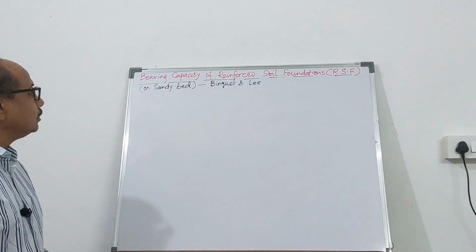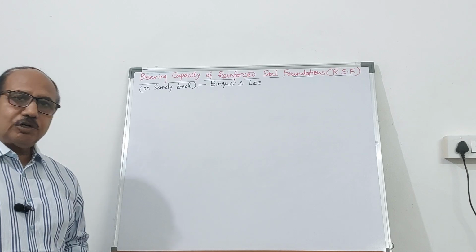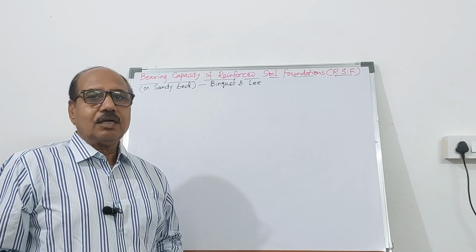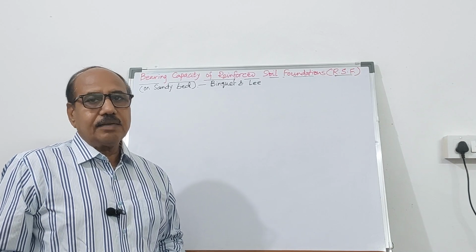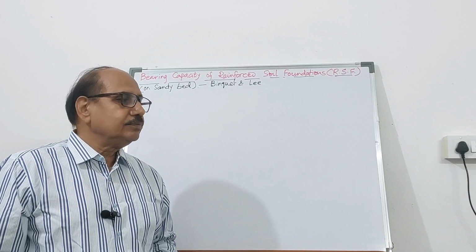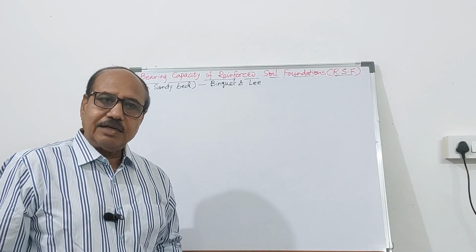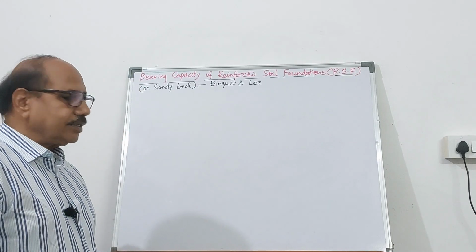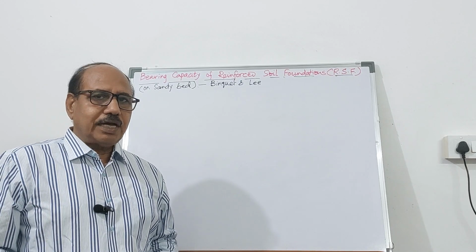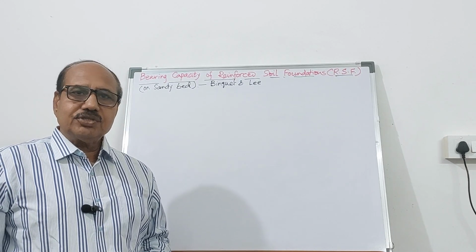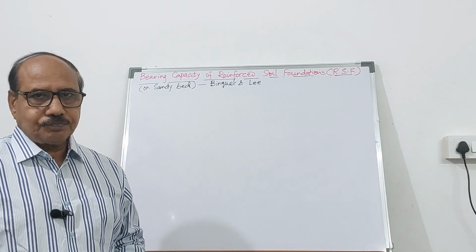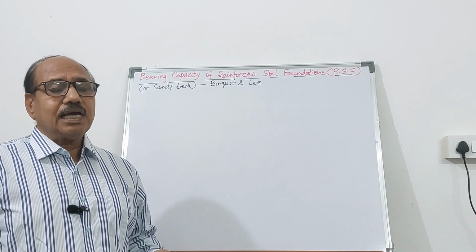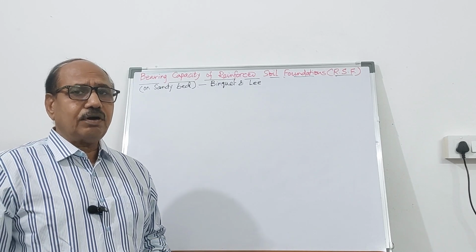Hello friends, in my previous video I talked about geosynthetic materials for improving the ground condition and also for improving the bearing capacity of a foundation soil. You can also have considerable reduction in settlement, and if you remember, I have already mentioned that bearing capacity can be enhanced 3 to 4 times.